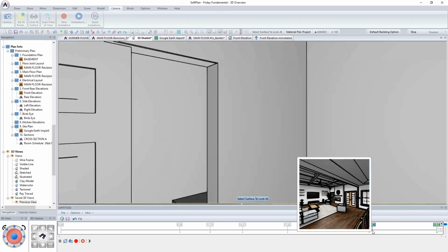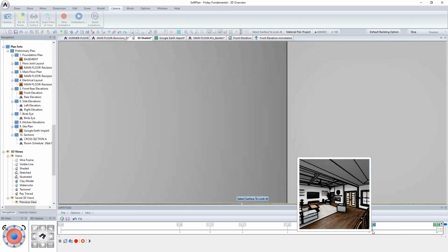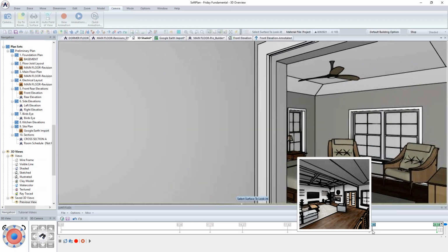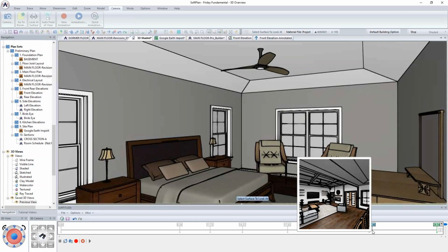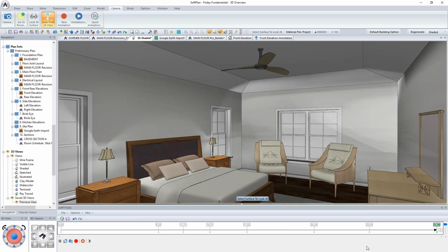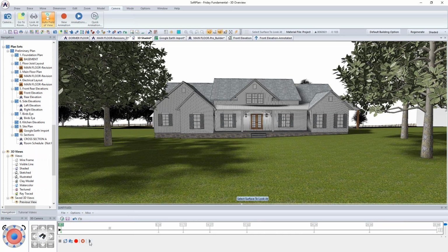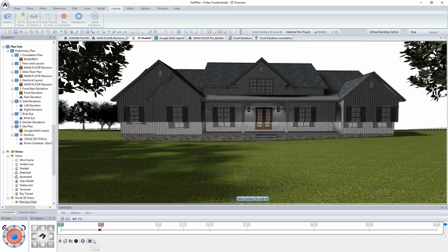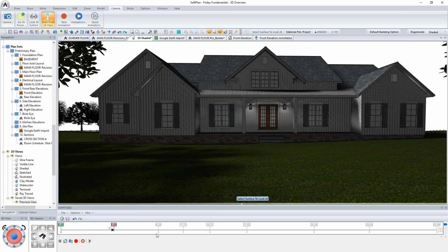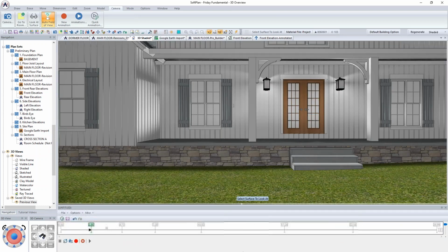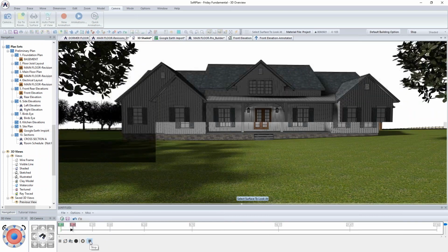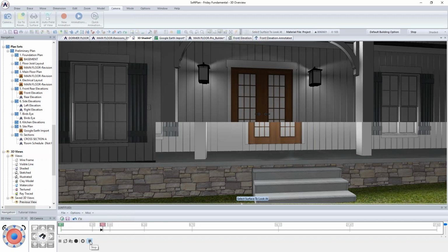And now I can pick up there, and we're going to maneuver around just to simply look inside the bedroom over here. Okay, and so as I do that, I will stop. So all I want to do to see this keyframe or see this model now is I will just click the plus sign, and I'm like, okay, as I'm doing this, I'm realizing that's taking too long to get inside. I can adjust and even speed up the frame just by holding down the mouse wheel and adjusting this. So now we're moving much quicker. That's better for what we're trying to do.